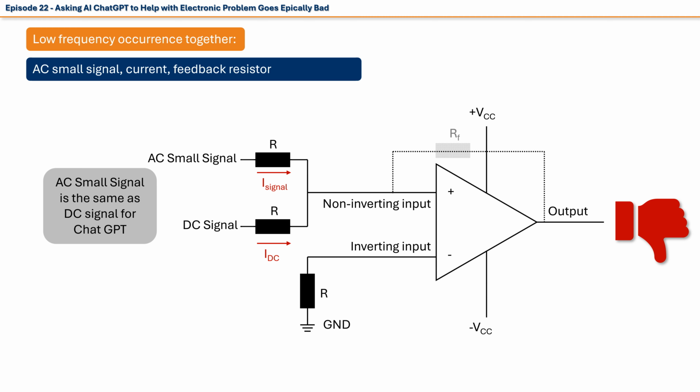It simply assumed that AC signal is the same as DC signal, because of frequency of word signal. It did not take into account that operational amplifier sums currents from those input signals, not voltages. Voltages in parallel cannot be summed, since 2 points in parallel have to have same voltage, otherwise laws of electronics fly out through the window.